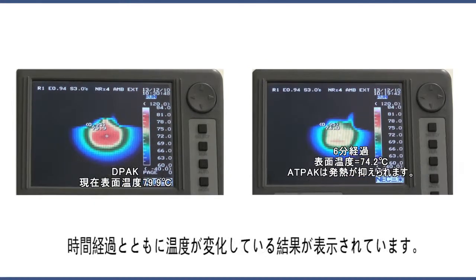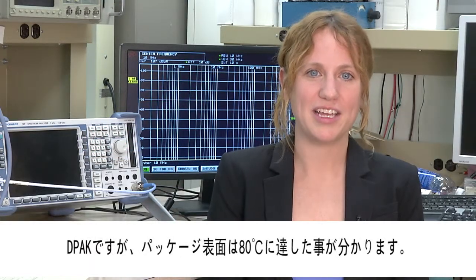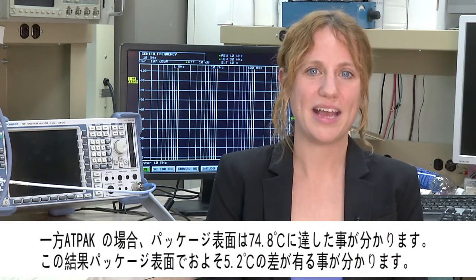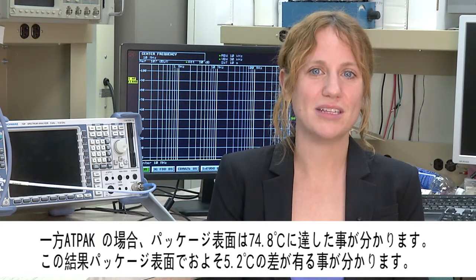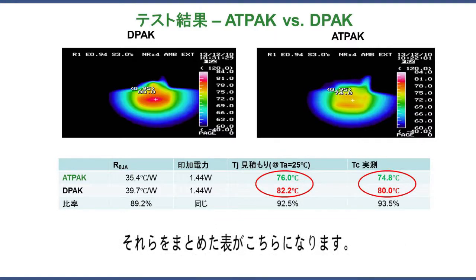Here are the results over time. You see that the surface temperature of the D-Pak package reached 80 degrees, whereas the surface temperature of the Atpak package reached only 74.8 degrees. This is a temperature difference of 5.2 degrees. If we estimate the junction temperature based on the thermal resistance, our calculation shows that the gap was approximately 6.2 degrees, which validated the test result. The table here summarizes the test result.